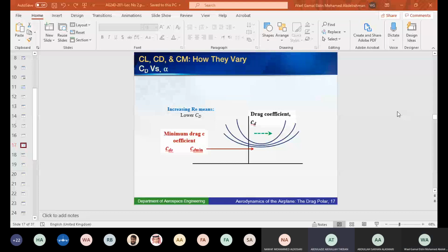I'm not sure, but I think the aerodynamic center is the point where the aerodynamic forces are in equilibrium. The point at which aerodynamic forces are in equilibrium. Well, I have a couple of problems with this definition. One, aerodynamic forces and inertia forces and the weight are always in equilibrium if we're talking straight and level flight, right? So it doesn't seem to be very accurate. Okay, who else?